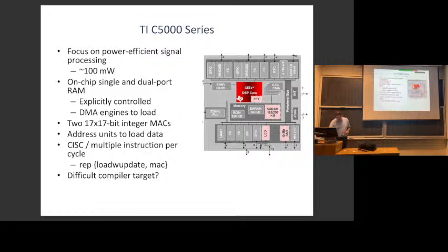Basically, that turned out to be a pretty good idea for a low-end DSP that wants really low power consumption. It isn't a great idea if you want to go to higher performance, because it's difficult for a compiler to automatically make instructions like this. A human can hand tune it, but a compiler has trouble. Okay, so I guess I answered that. This was a hard compiler target.